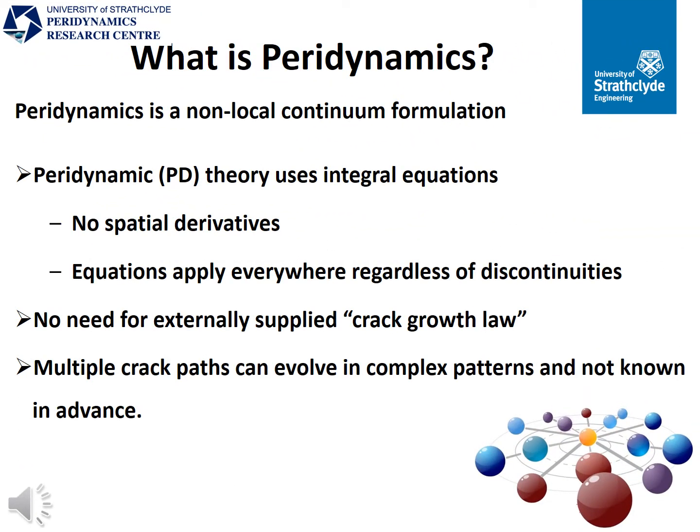So, what is peridynamics? It's a non-local continuum mechanics formulation. In peridynamics, we use integral equations rather than partial differential equations. Therefore, whether we have discontinuity or not, equations apply everywhere. And peridynamics is especially good for predicting failure. And we don't need to use any crack-growth law for failure prediction.